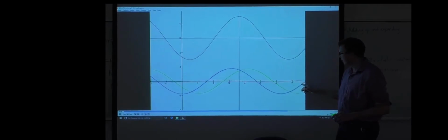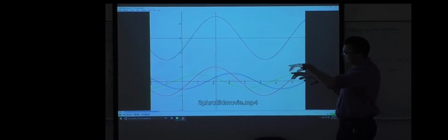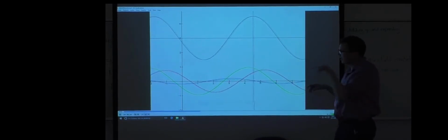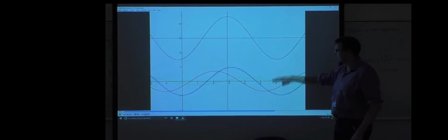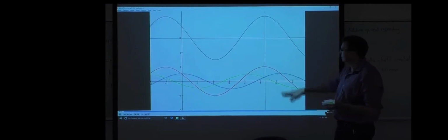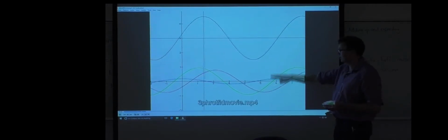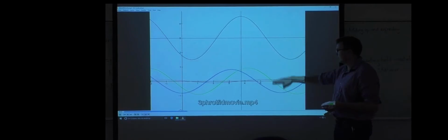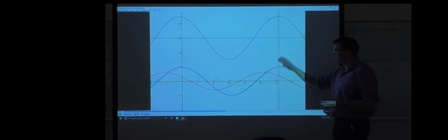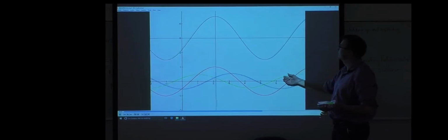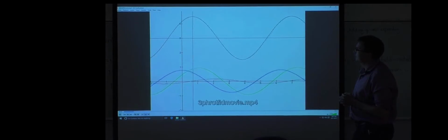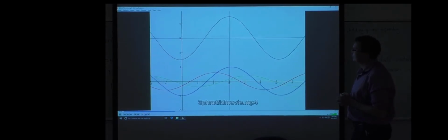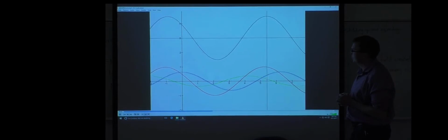This would be the winding distribution, which creates this waveform, and then we apply a current into it that changes the magnitude. You can see that they are oscillating up and down, but that's not going to be useful for creating rotation. But when you sum them up, it creates this traveling field, and it's really quite clever. That's what we want to create.